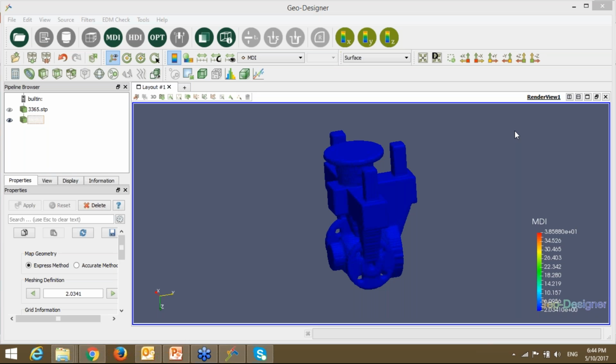So this will ensure, more or less as a thumb rule, not precisely 100%, but you will be 80% correct in deciding your riser size, your feeder location, and whether a chill or sleeve will be required. So it will drastically reduce your time to decide all this without foundry trial and simulation. That is the purpose of that. You are even reducing simulation time.